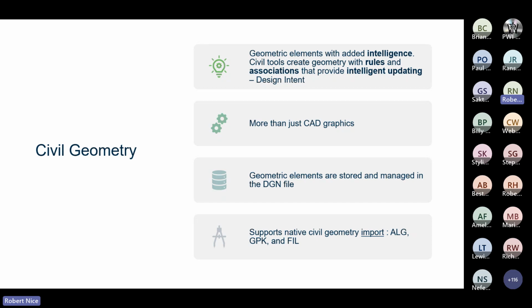So an example, I've got my terrain model. Maybe I've created it in a different file, I've opened up a new file, and I've got my geometry. In that geometry, I can reference in, so a 2D seed, I reference in my 3D terrain model. I can then do a profile on my horizontal. I can display, I'll see under display my ground. I can snap to the ground for my vertical piece of geometry. So then if I move my horizontal, my vertical would move across, but stay snapped to the ground. So obviously things may change, elevation, stuff like that.